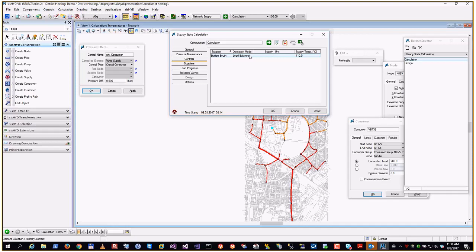Okay, with the mass flow, we can compute the heat loss. But the heat loss, we do not know upfront. The heat loss along a pipe depends on the mass flow through the pipe. So we know the demand, 140 kilowatts. But the supply station has to feed in 140 kilowatts plus a little bit. And that is to account for the heat loss in the network.